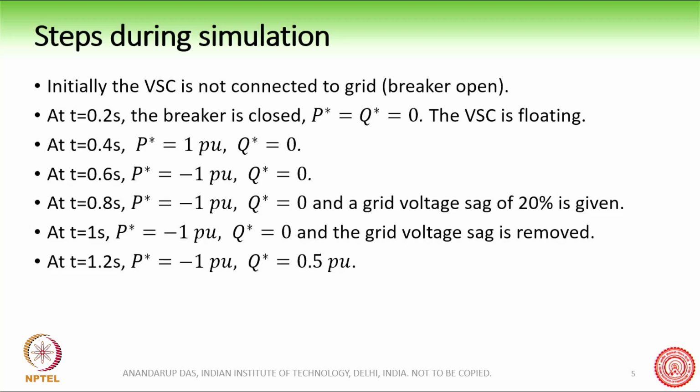It is as if like a synchronous machine. When you connect to the infinite bus bar, at first the synchronous machine is excited from a prime mover and the voltage is generated, but the breaker is open. In a similar way, the VSC is fed from the PLL, and the DC bus, here we have assumed the DC bus to be constant and it has already been pre-charged. In practical scenarios, sometimes we require special techniques to pre-charge the capacitor.